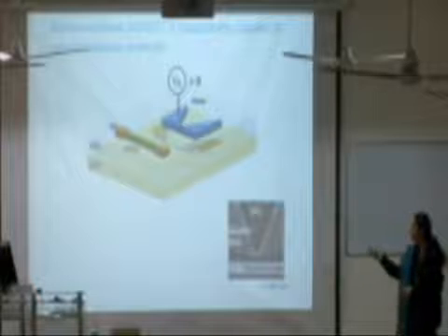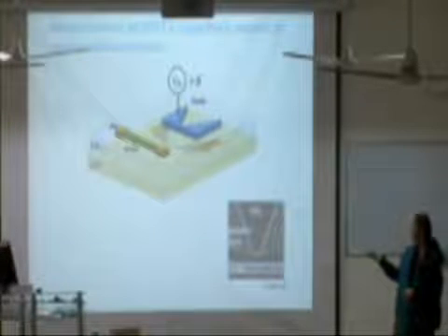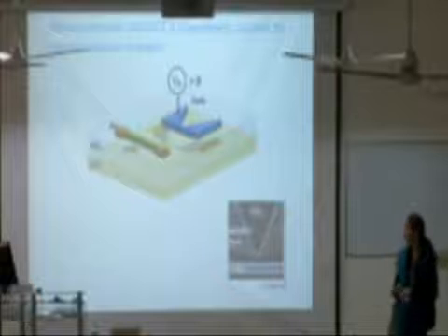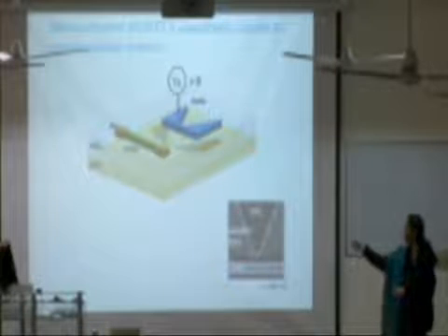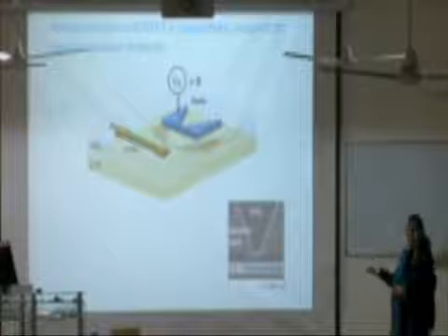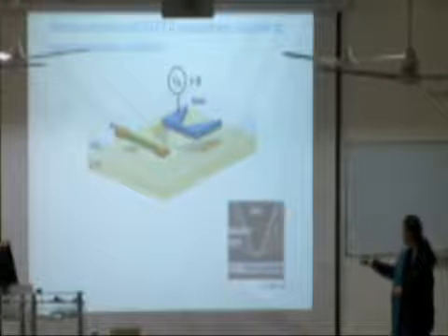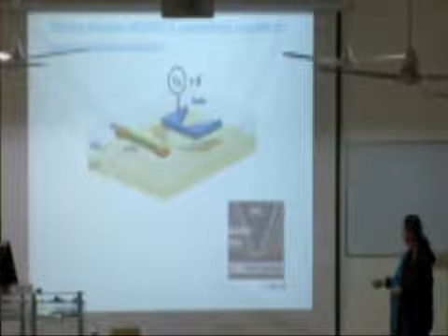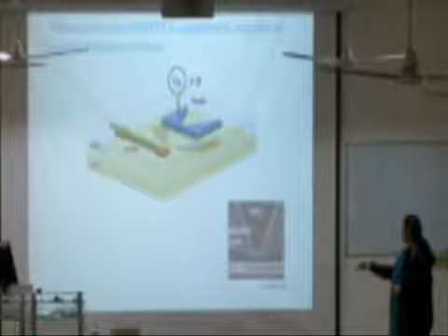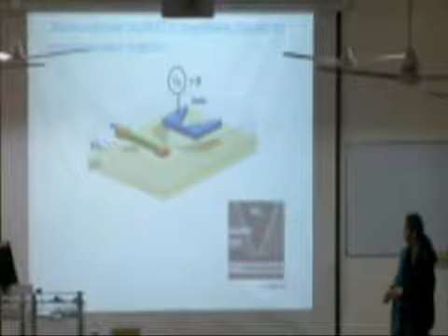So now we want to use this MOSFET to study transport in this resistive material. We start with amorphous germanium, which is an amorphous semiconductor, and we pattern amorphous germanium in front of this sensor. Here's a scanning electron microscopy image. This is our MOSFET gate, and it tapers down to a width of 70 nanometers. And here's a strip of amorphous germanium that we've patterned 100 nanometers from this sensor.